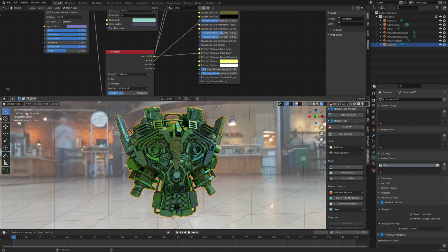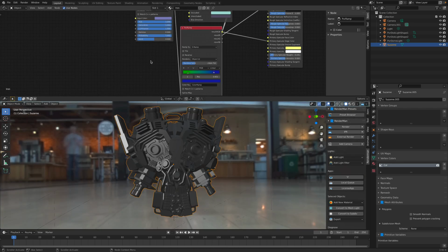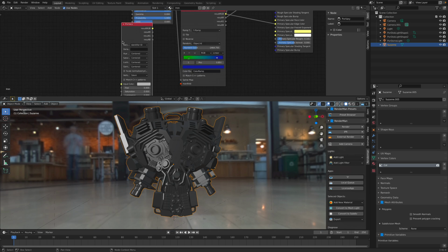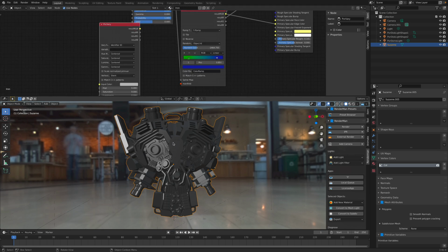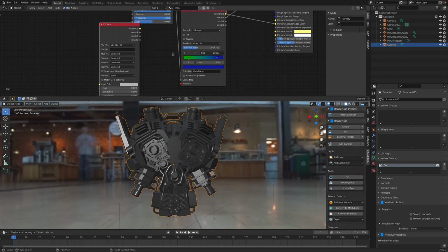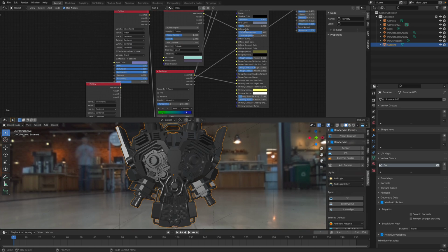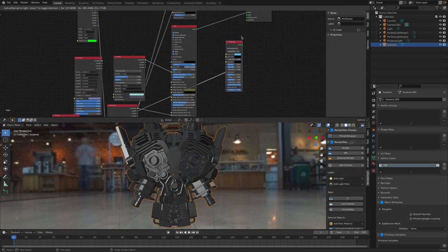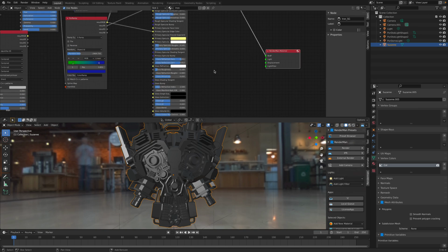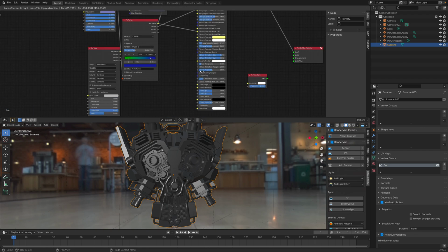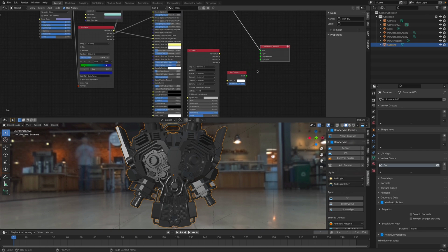There is a way to use something called PxrVary. This PxrVary can give you a different color based on different parts of objects if they are actually separate. Currently, this is a single object. Let me try to show you. So this is the final output, right? I will use Pixar constant. Let me try and see if this works using the constant BxDF.